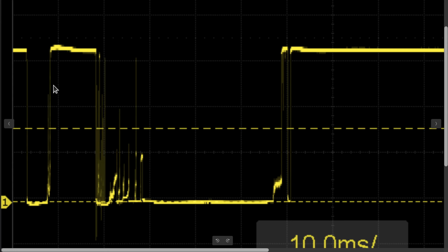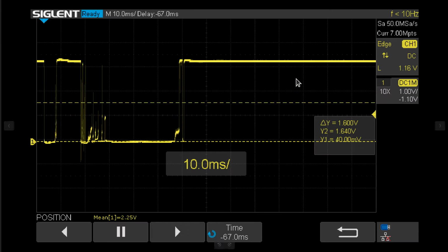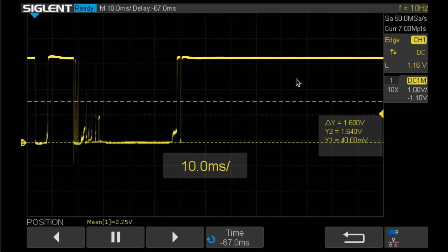If you just peck this thing once and you're hooking it up to something like a counter, it might look like it counted 1, 2, 3, 4, maybe even 5, 6, 7. These might not count down there. 8, this one swings down, maybe 9, and then 10. I mean, it might look like you pushed it 10 times. And we've all seen that happen. A really garbagey bubble membrane key on your washer or your microwave or something, when you're trying to set the time and the darn numbers go up at the wrong speed because some dingus didn't take 5 minutes to debounce that switch.